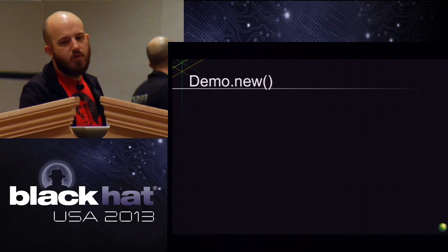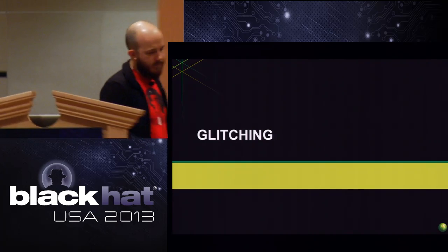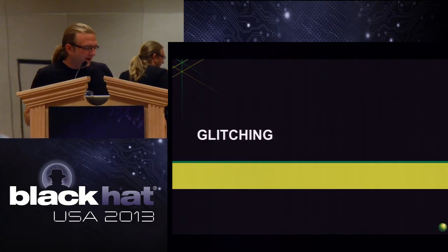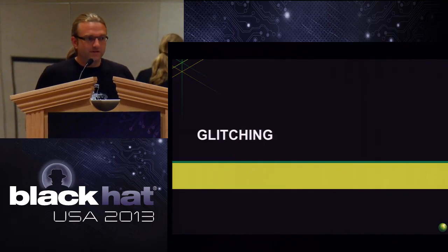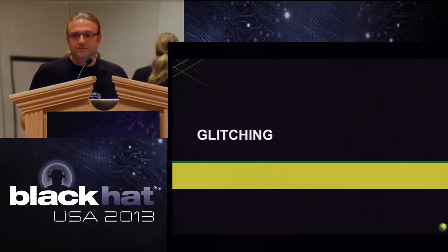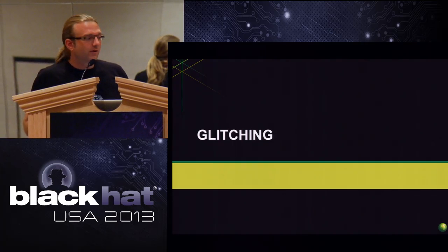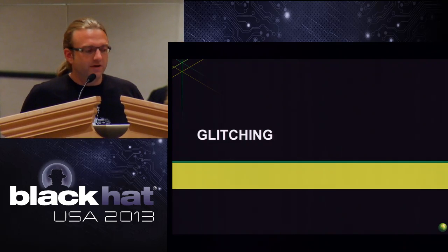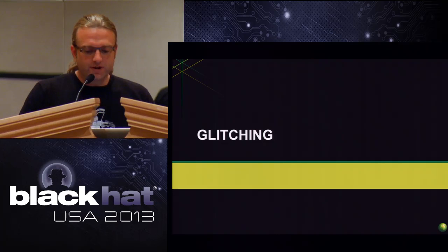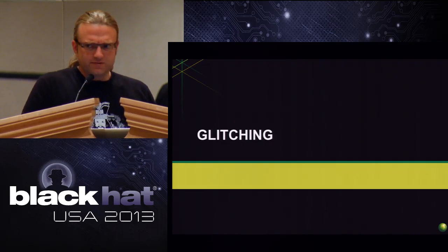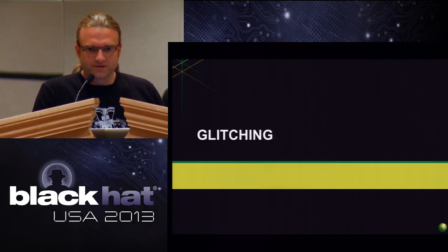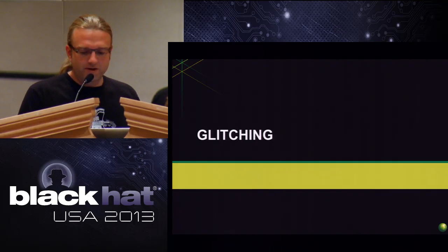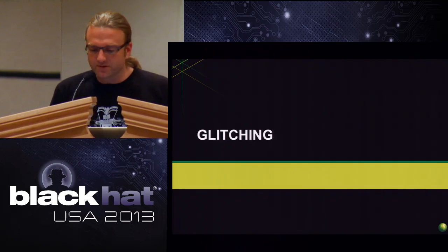I think we've got a couple minutes that we'll cover glitching real quick. If you remember way back, we talked about there's some bits that can be set that don't let ICE be enabled anymore, so you can't actually do any live debugging on the board, unless you magically hit it within that first 30 to 60 cycles. Once you do, you can get away from that. But we kind of wanted to do something a little sexier, and it was one of the reasons we're not releasing the Goodfet code, because we went tangential down this path and the Goodfet just couldn't quite keep up with where we wanted to go. We will get there and release it hopefully at some point.